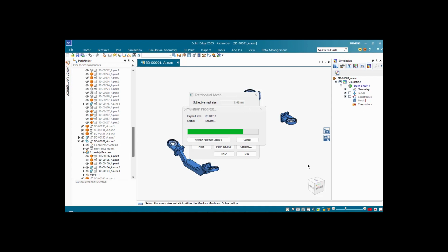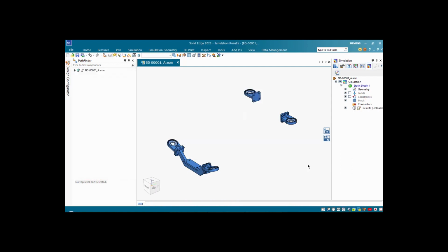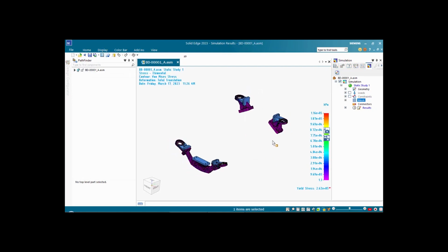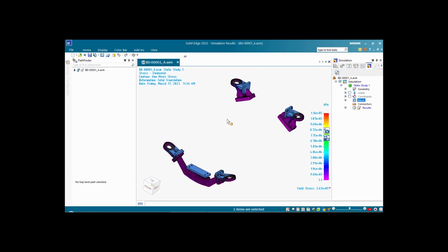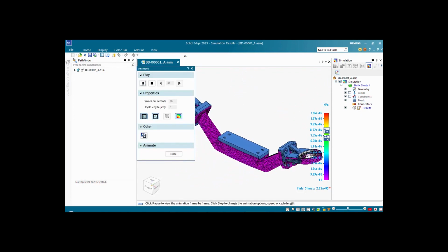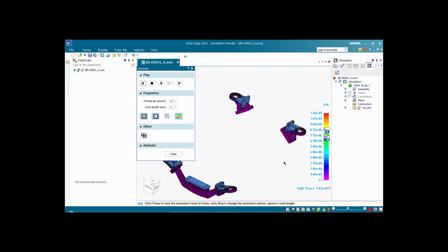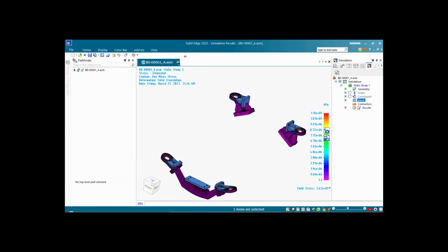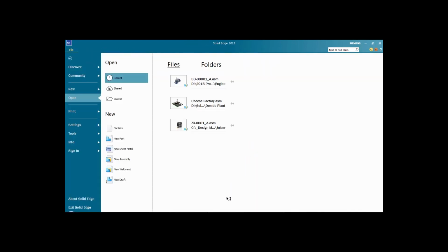You can get results quickly in no time just by using this unite command that will unite for you even disjointed components in assembly. It provides really efficient and fast way of analyzing your assembly without actually, let's go and animate this. Provides really great way of analyzing your support, in this case, support subassemblies versus trying to create additional connectors, introducing additional geometry, and so on. So this is a great way to quicker results and in the most efficient way.